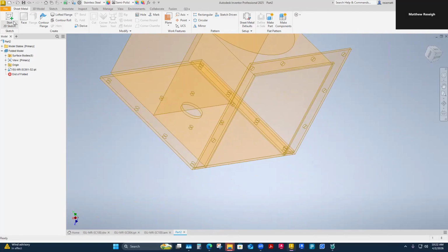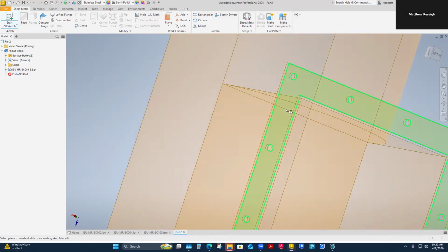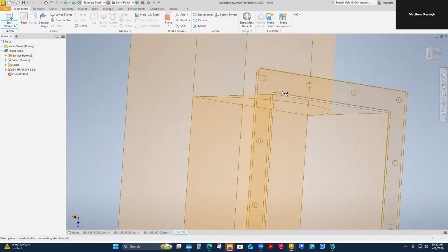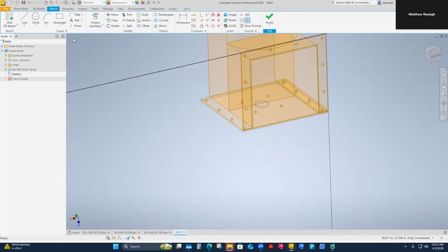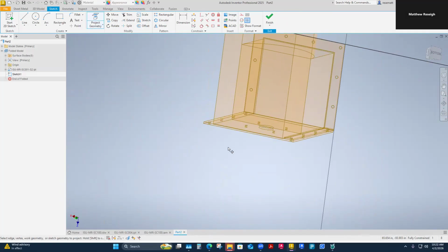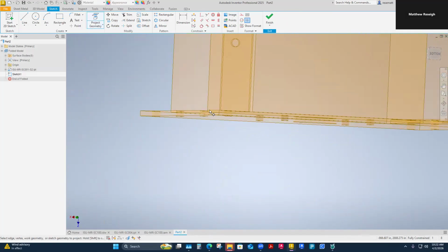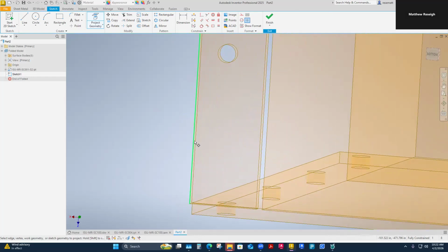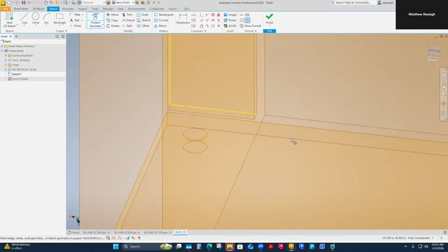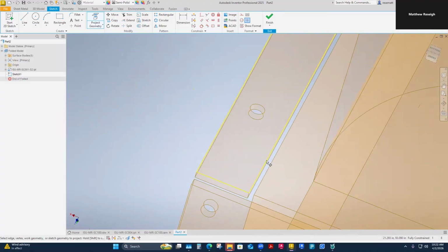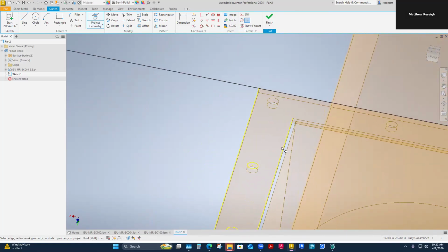If I create a new sketch, I'm just going to make it on wherever. You could choose this surface or this surface to make it from. I'll just choose the bottom surface for no real good reason. And then I'm just going to use projections only. No dimensions. If I ever update this solid, I would want it to accept those updates. And so by using projections, I eliminate having to do any constraining or dimensions or anything. And then those projections should update automatically with an update to the solid underneath it.